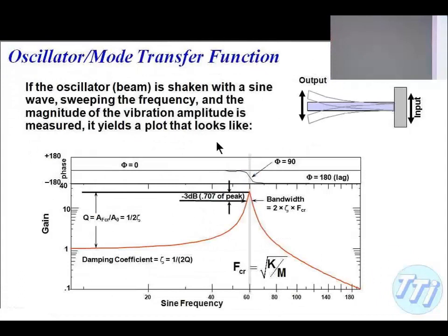And when we do that, we wind up with a transfer function that's got a gain of 1 at low frequency and peaks up at its natural frequency, and then above the natural frequency it tails off. And it's a two-pole filter, so how fast does it roll off out here? 12 dB per octave, okay? 6 dB per octave per pole.